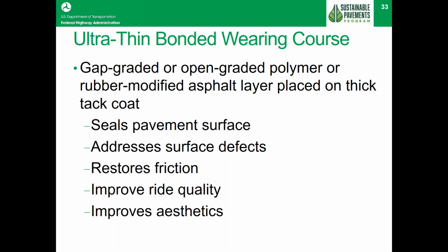These are often placed in very high traffic highways. You'll see them on interstate highways, see them on urban freeways, and some of that. Frequently used a lot to improve safety and extend the life of the pavements. The safety improvements are usually related to friction improvement and correction of things like rutting. These do require a lot of attention to detail, but the surface can take a lot of abuse, and they tend to last for a long time on the roadway.